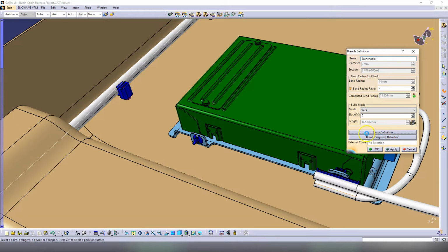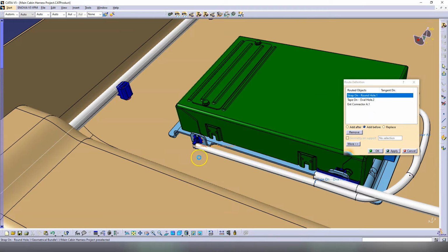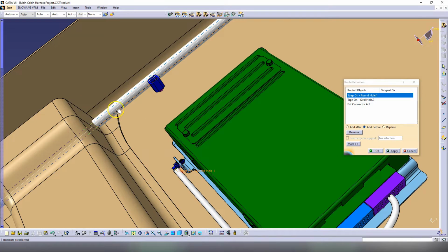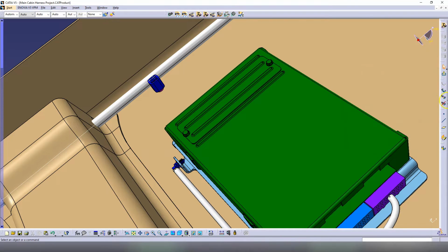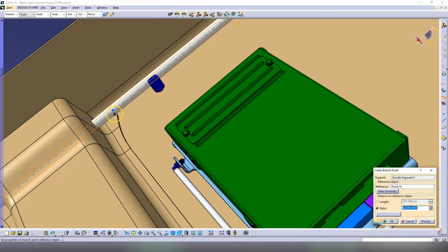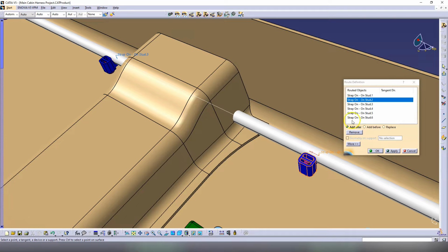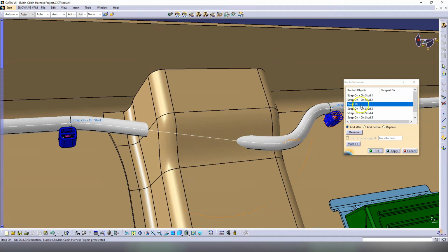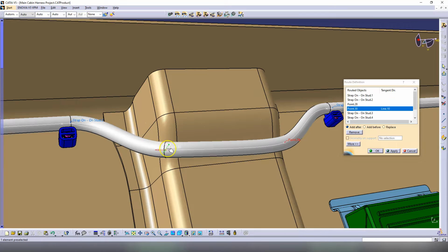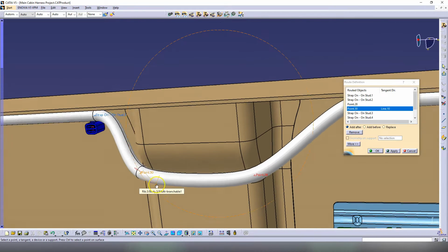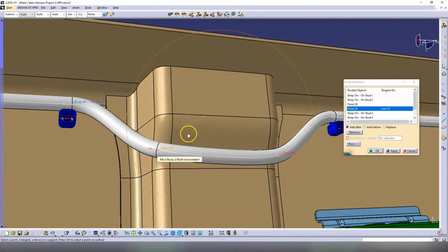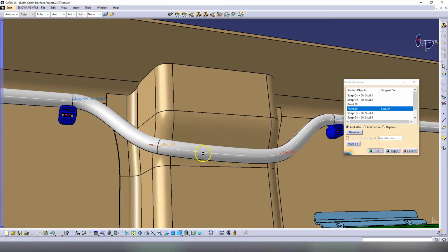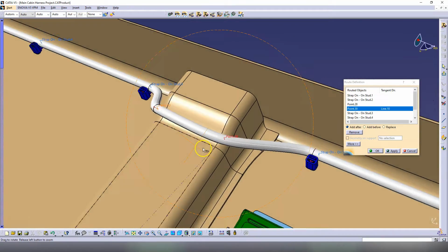So from here, let's go add before here, and from here we go. I need the branching point on the main bundle here. Say I add it in this area. So here, this one add after, and we do something similar in the course, but I explain in more detail what you have to look after here, what the problem can be, what DFMA problems you can have with this one here, why you cannot add any retainers in this area, and so on.